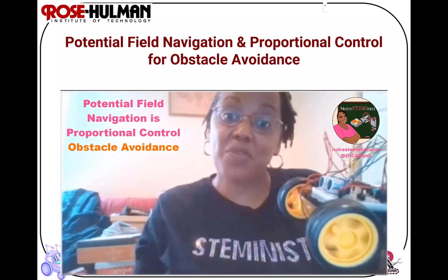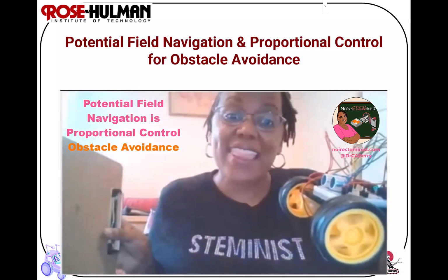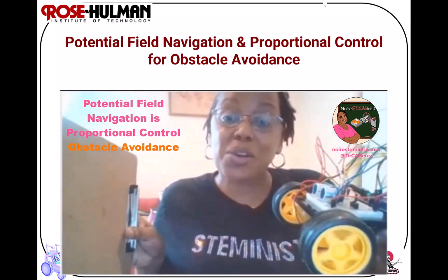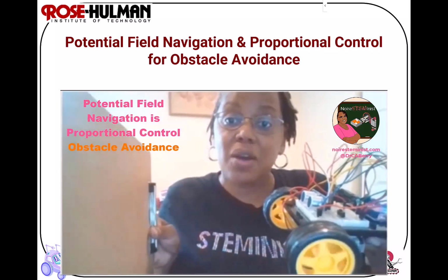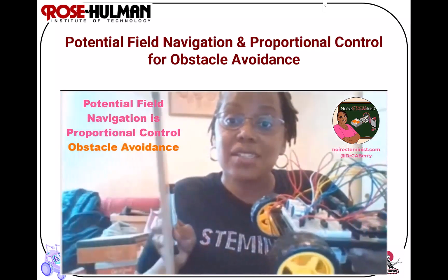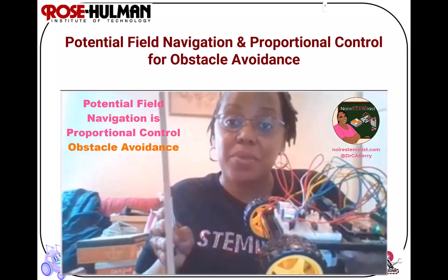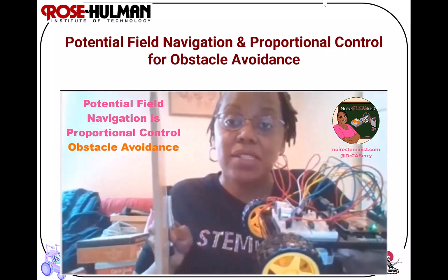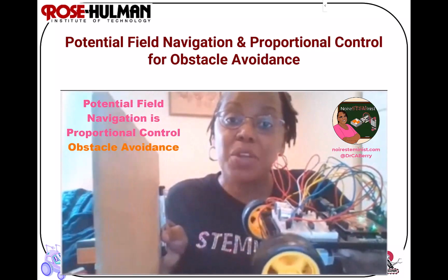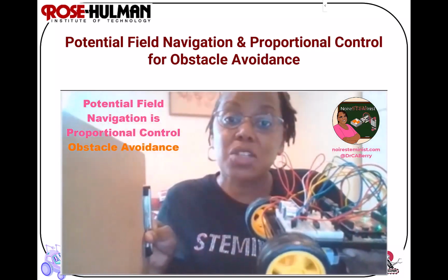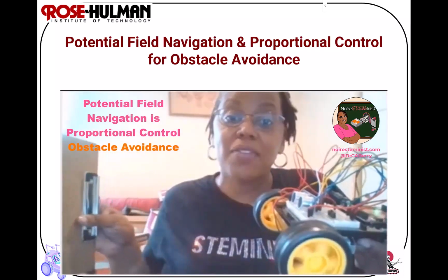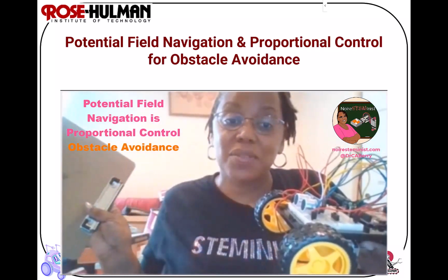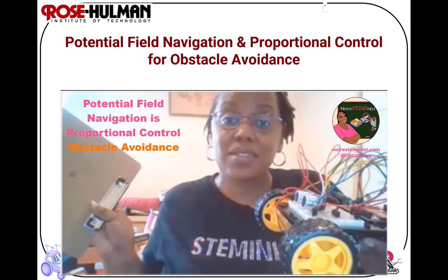All right, here we are full speed ahead. Then as the obstacle gets closer, proportional to how close it is, the robot slows down. When it gets within 5 inches, it stops. Now, obstacle avoidance is not only about not hitting, but moving away. So it's going to move away slowly, and as it gets further away, it moves away faster. Then once it's in the clear, it stops.